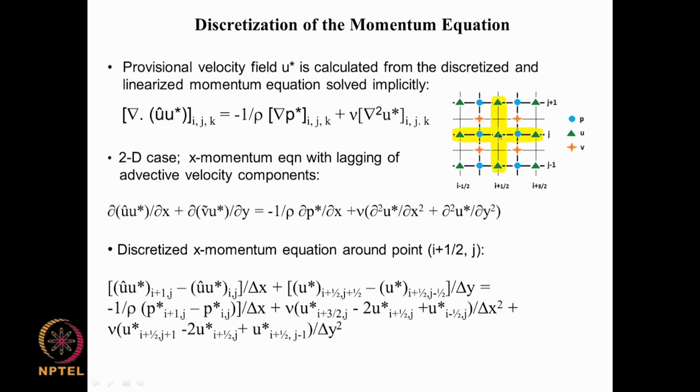If you are making use of central differencing, that is what we would also use for this, but if you are making use of the upwind scheme, then this u star at I plus 1 here is taken to be this value, that is the upwind value, if u is positive, and this value if it is negative. So, if you are using the upwind, backward differencing scheme, in the case of u being positive, there are 2 velocities, u star and u tilde, which is from the previous value, and this is the current value.